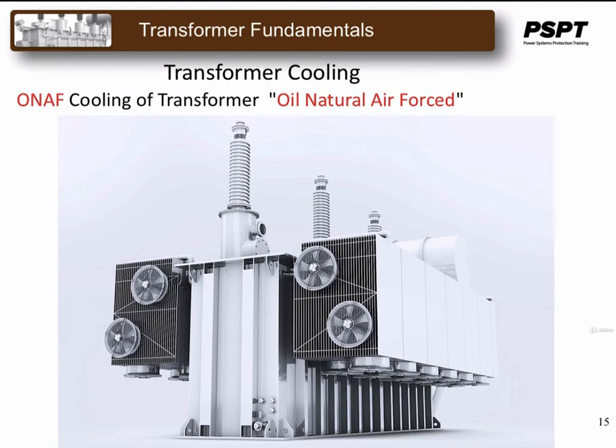Forced air takes away the heat from the surface of the radiators and provides better cooling than just natural air convection. As the heat dissipation rate is faster, electrical power transformers can be loaded more without crossing the permissible temperature limits. The air forcing fans are sometimes switched on and off in stages, providing stage ratings for the transformer.